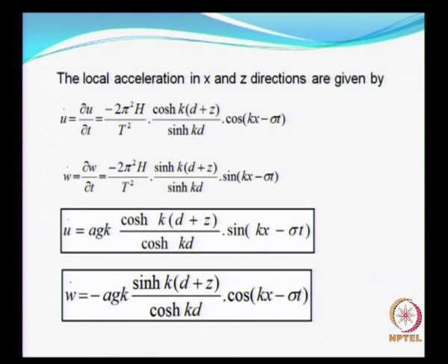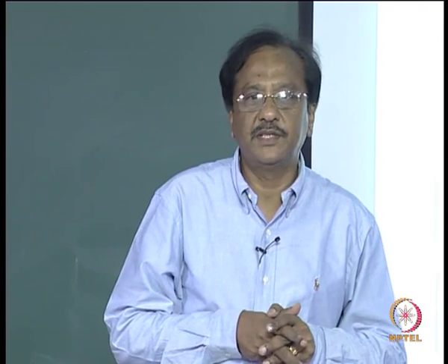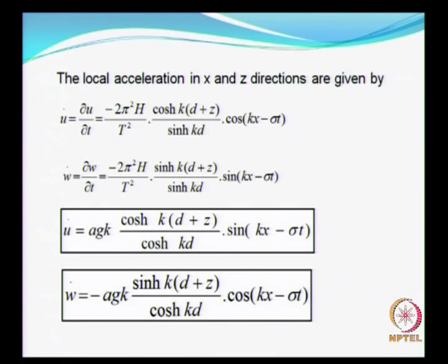Now we proceed further in order to obtain the acceleration. Waves are an unsteady flow, so the fluid properties vary with respect to time. When a wave is acting on a pile or a structure, the forces induced on the pile will be due to both particle velocities as well as accelerations, which we will see later. So in order to obtain the total force, we need the particle accelerations also,